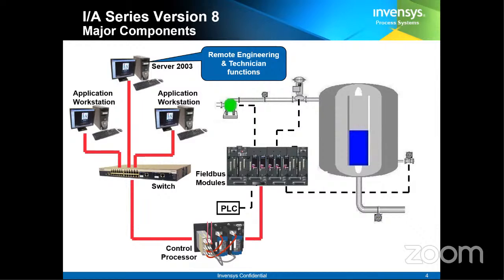In the case of the Foxboro DCS system, the count varies from 0 to 32,768. Based on the different systems, these counts are designed or calculated. Ultimately, they transmit the analog signal value that comes from the field into digital form, and that value goes to the control processor.